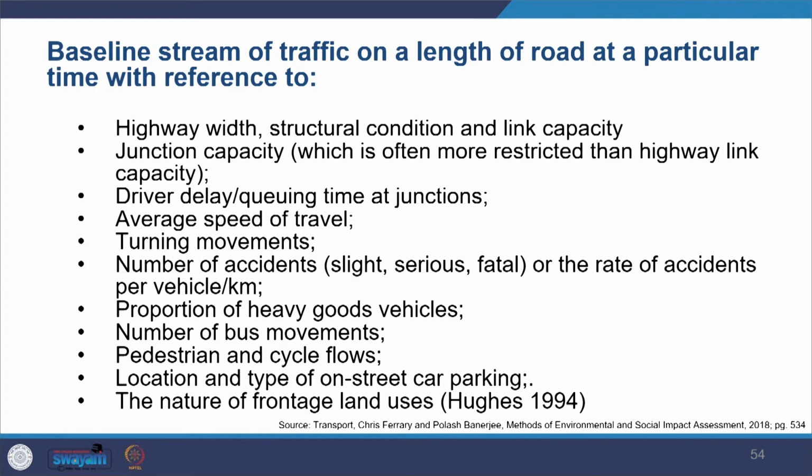It's also required that you describe the baseline of traffic on the entire stretch which you're working on. You need to look at all these details: highway width and junctions, the delay which will happen, average speed, the turning movements, number of accidents, and proportions of heavy goods vehicles. All that has to be given. Plus you need to give the number of bus movements, pedestrian and cycle flow, location and types of on-street car parking, and the nature of frontage land uses.